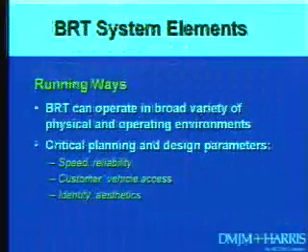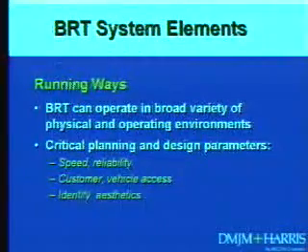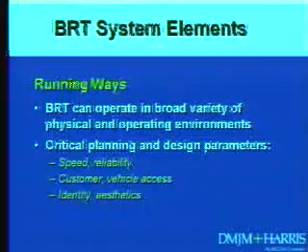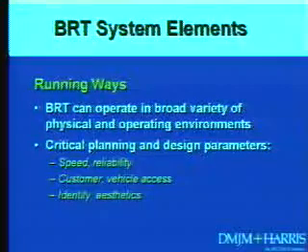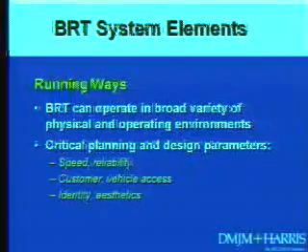So the second thing then is the running ways, or some people would say right-of-way or roadway or whatever you want to call it. I mentioned before that BRT can operate in a wide variety of running ways. It can be all by itself in a tunnel or elevated, real expensive, can be on arterial streets, can be on an HOV lane, can be on contraflow lanes, can be just about anywhere that a vehicle can operate.